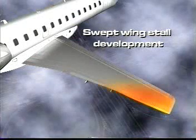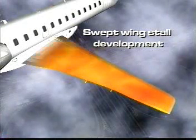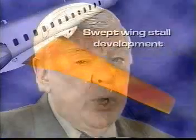If an actual wing were allowed to stall in this fashion, aileron buffet would occur, and the wing would drop. No nose-down moment and very little aileron effectiveness would be felt. When sweep back and taper is combined in a wing, the tip stall tendency is further aggravated.